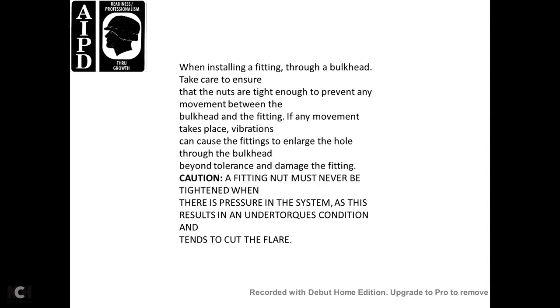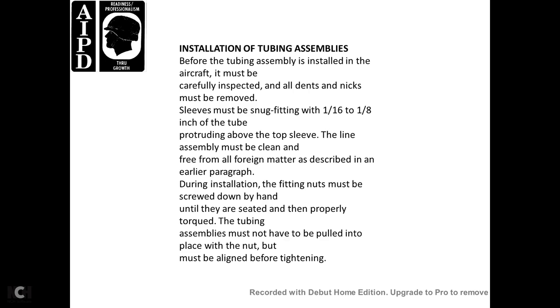When installing a fitting through a bulkhead, take care to ensure that the nuts are tight enough to prevent any movement between the bulkhead and the fitting. If any movement takes place, vibration can cause the fitting to enlarge the hole through the bulkhead beyond tolerance and damage the fitting. Caution: a fitting must never be tightened when there is pressure in the system, as this results in an under torqued condition and tends to cut the flare.